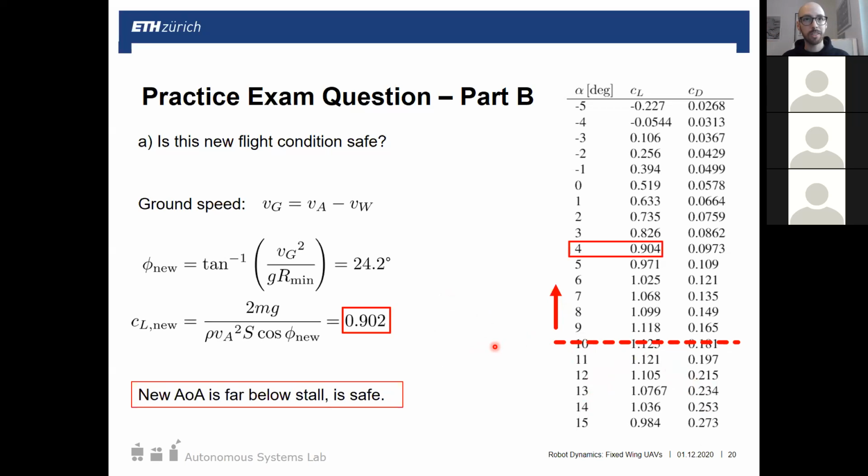So if you're interested in deep stall, it's actually pretty cool. You can go to YouTube and type in deep stall. Maybe you'll see some RC pilots doing an example of it. But basically your flow is almost totally separated on the wings, but you enter a condition where you can actually stabilize as long as you have a full moving horizontal tail that can regulate your pitch.